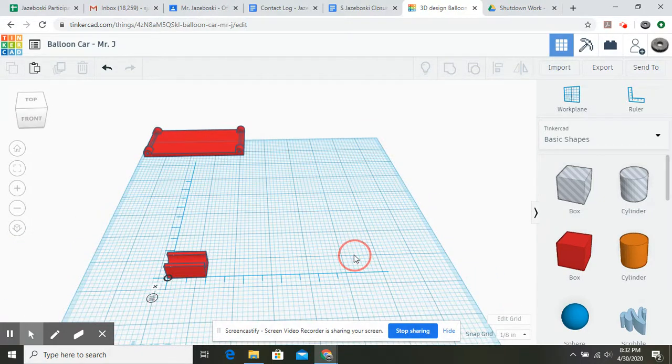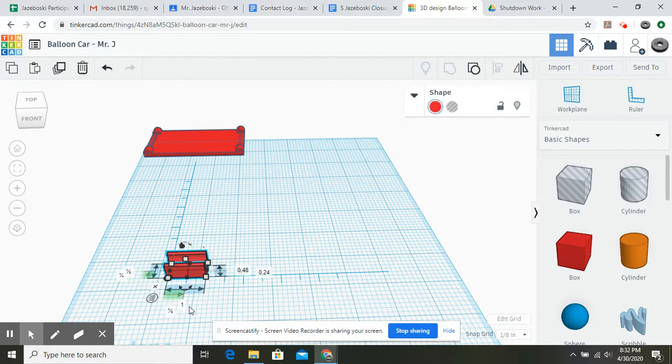Now, when that's done, what we're going to do next is move the position of this to where it's going to line up with our base when it's done. We're going to leave it on midpoints for now. When I put this on here, it says use endpoints, and we'd change it for the endpoints, but we want to leave it on midpoints. And then we're going to change the X to 2 inches. When we do this, remember, we want this green arrow to light up.